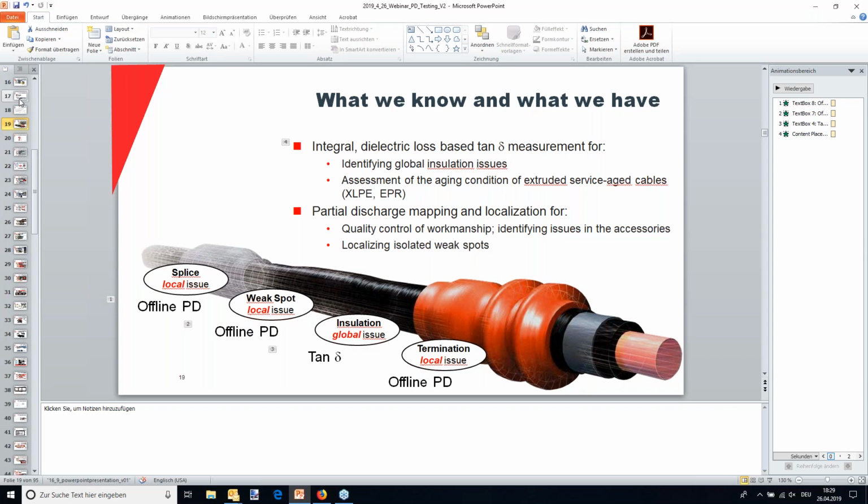We have solutions as well for monitoring medium voltage switchgear. That would be the product called PD Scan. And for high voltage transmission environments, let's say the high voltage end terminations, there's the UHF detector, so the non-conventional measurements. But that is more like substation monitoring or substation testing. On cable, that is a whole different animal in terms of PD.